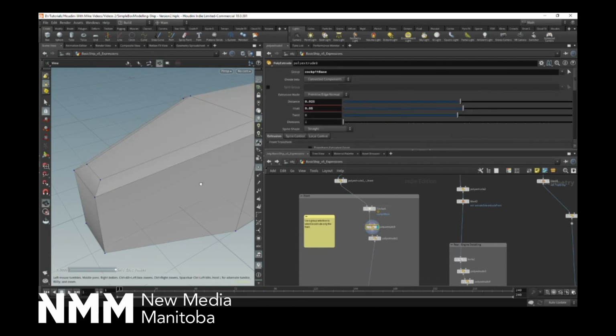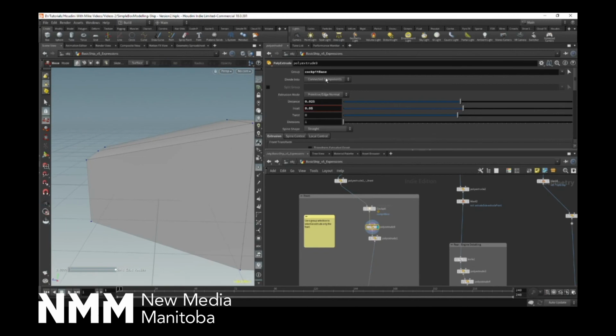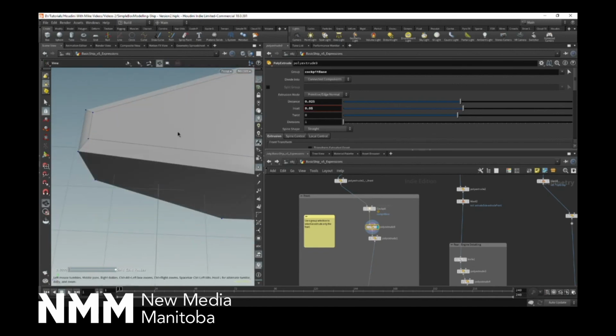Now I'm using extrude in two different ways here. The first time I'm using connected components, so it's actually extruding this as one piece. And then I'm just going extrude. Oops. So let's just divide this a little bit. There we go. And then the second time, I'm dividing into individual elements.